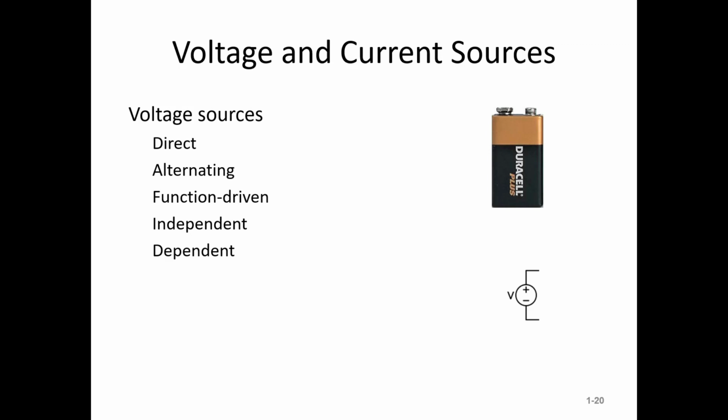So the way they do that is they monitor the bus voltage, and as it goes up and down a little tiny bit from 14, there's a current source in the alternator that correspondingly adjusts.